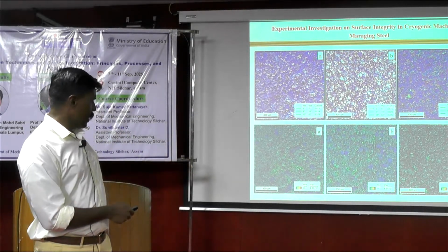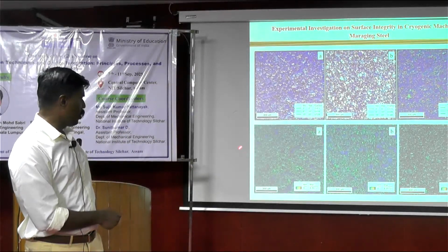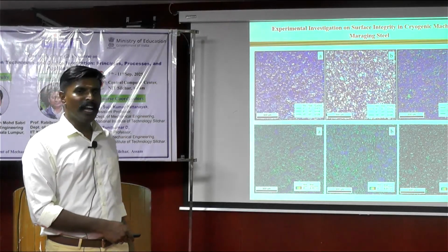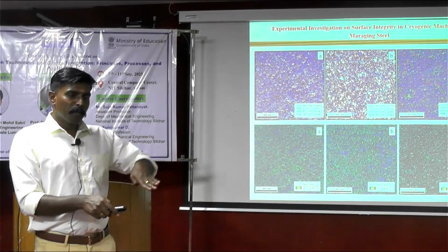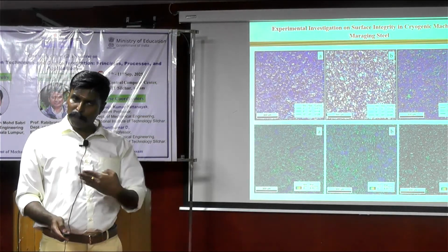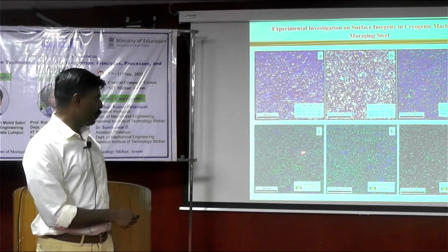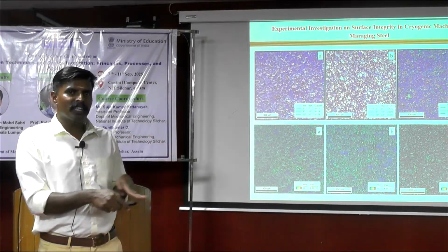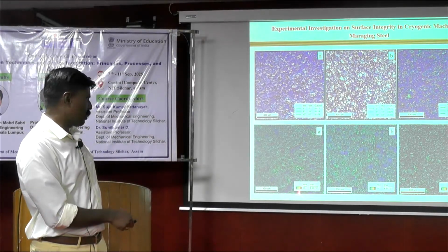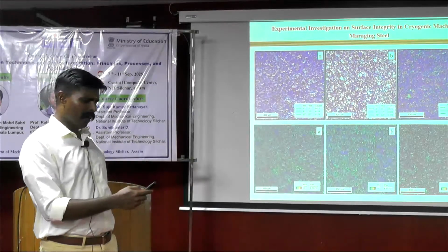Okay. So here this is called KAM, kernel average misorientation angle. During machining, machining is nothing but some deformation happening, so some stress is developed in it. This map is showing the strain accumulation in it. Wherever the scale shows, almost everywhere the material is strained.